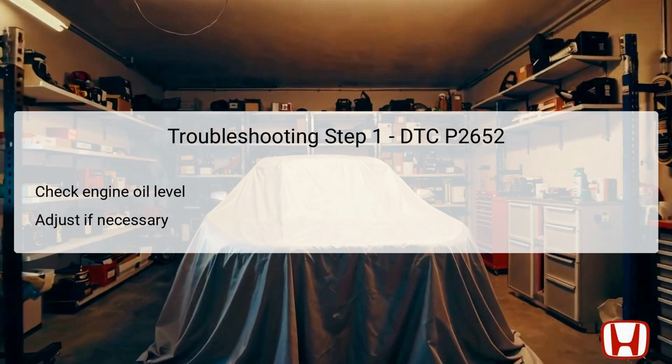Always verify that no oil leaks are present, as these could again lead to low oil levels, affecting both the switch and the overall engine operation. A simple level check can save a lot of time and resources if this proves to be the issue.